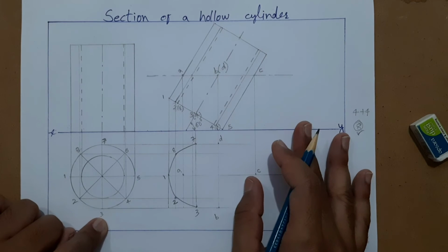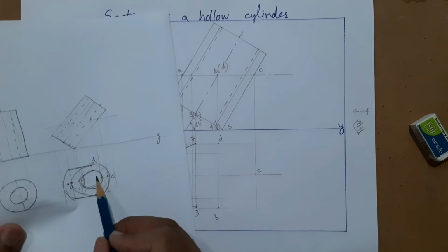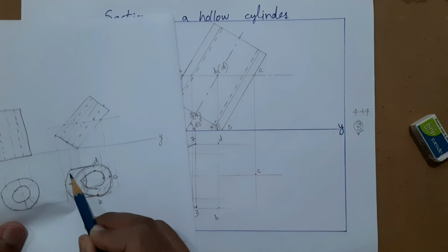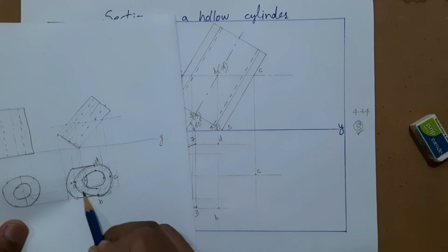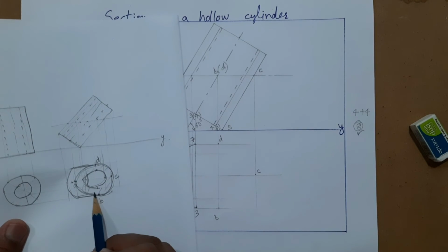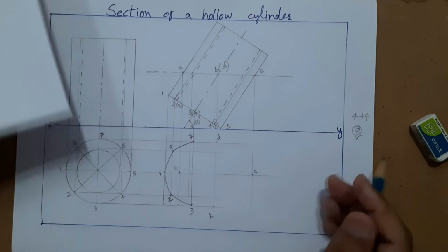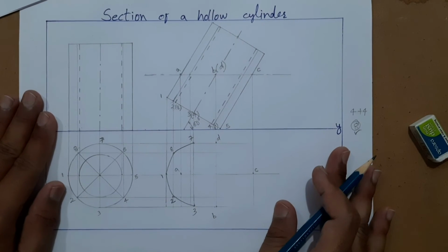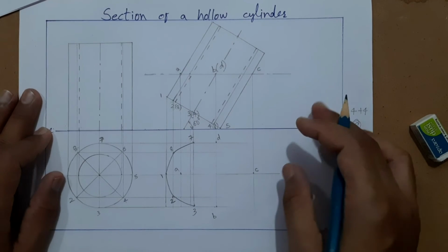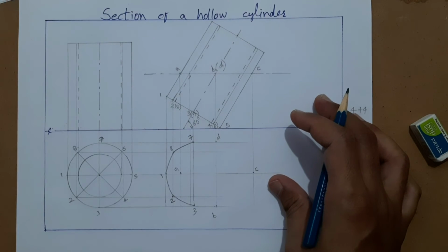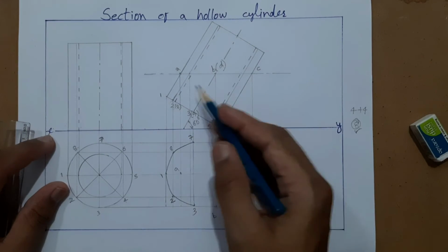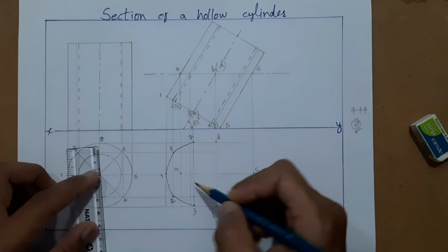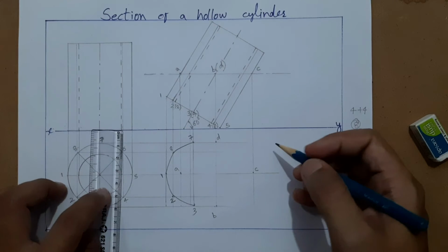Now we will concentrate on this section, this internal. After cutting, a new surface is generated, this we have constructed, this we will construct now. Then we will join this line and this line. Then we will go for the internal part. Step by step we are going to avoid confusion, and there are so many projector lines coming one after the other, so you should not get confused. Circle 8 parts will do. Those parts are here. This side portion we are not taking as of now.